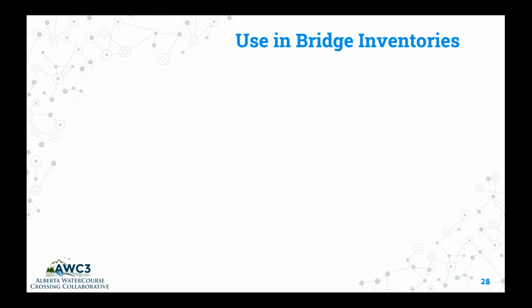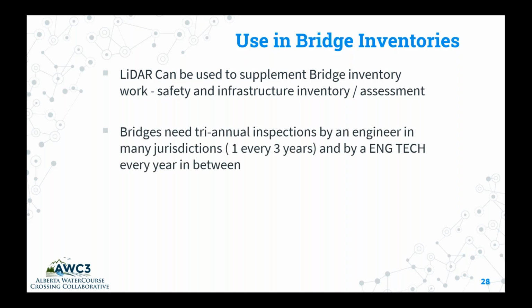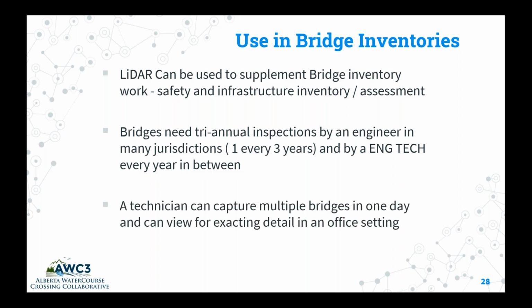Now, talking about the bridge inventories, LiDAR can be used to supplement bridge inventory work, safety and infrastructure inventory, as well as assessments. Now, in most jurisdictions, a triannual inspection is needed by the engineer, one in every 3 years, and an engineer tech has to go out and do it every year in between.